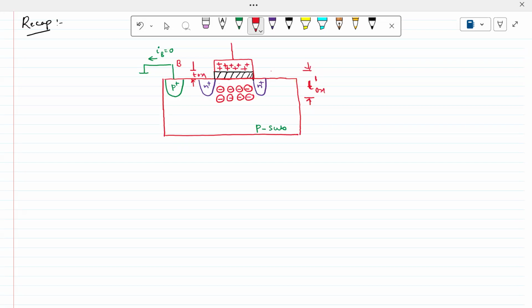Now, if you further increase the positive charge on the top plate, due to the lower capacitance, the carriers cannot be depleted. As we have mentioned, it is simply a MOS capacitor, right? Therefore the capacitance is epsilon A divided by D, where D is the distance between the two plates. If the distance between the two plates is more, the capacitance will be less. If the capacitance is less, whatever charge you put is not able to induce the opposite charge on the other plate. The electric field is not able to deplete more carriers.